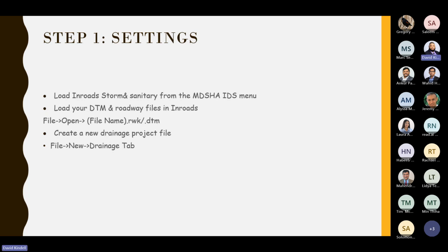So the first thing you want to do is go to file, new, and create a drainage database, Monterey Avenue. And you say proposed drainage. And you click apply. And now when you go to the different tabs here, to surface geometry, now you have drainage. Your project will show up in here.